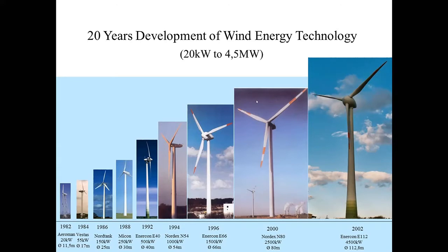But above 2 megawatt, it is no longer possible to work with these very easy systems. It means we need highly sophisticated systems, with pitch regulation and speed variable operation. It means with inverter systems. After 2002, we expected that in a short time we would come to 5 to about 10 megawatt. But these wind turbines were only extended to 6 or 7.5 megawatt, but not more.